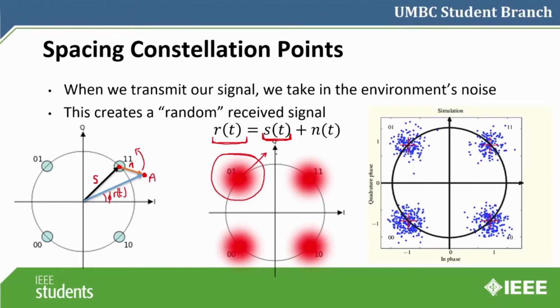And so what we're able to see is that the probability of getting an error that's all the way over here when you sent a 0, 1 is really low. But it also means that if you sent a 0, 1 and it's all the way over here, you're probably going to think that's a 1, 1 in the received signal. However, if we know how much noise our system has, we can properly determine the space between these two that we need such that this will very infrequently happen. I hope that makes sense to people.